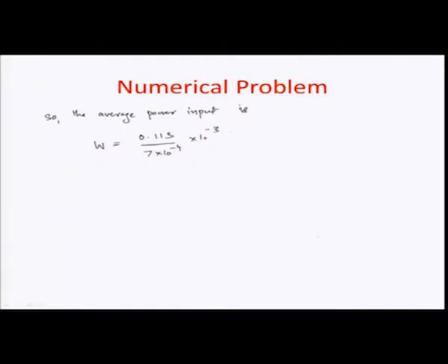So it's basically 10 to the power of minus 3 kilowatts, which makes it 0.16 kilowatt. And using the equation that we had discussed about mild steel, MRR can be represented as 27.4 times this value of W in kilowatts to the power of 1.54 in millimeter cube per minute. So this is an estimation of what would be the material removal rate. This in our case comes out to be equal to 1.633 millimeter cube per minute.